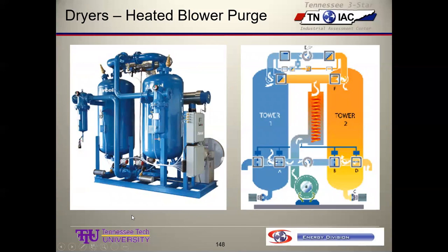So if you've got a heatless cycle, but you're regenerating it every 4 hours, then it's going to be blowing air for most of that 4 hours. But let's say it's the wintertime and you don't have much moisture load, so it doesn't really need to regen. It's not spent after 4 hours in the wintertime. But if the controls are simple time controls, then it just keeps switching whether it needs to or not. It doesn't know if it's spent.